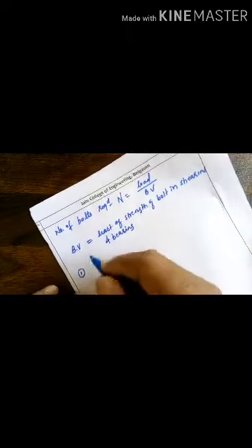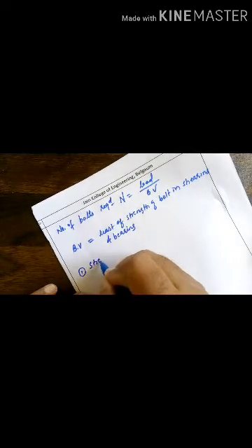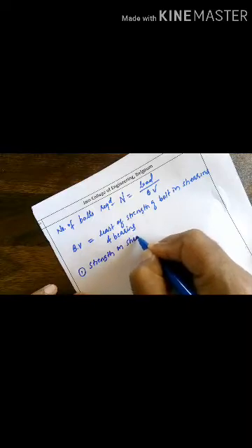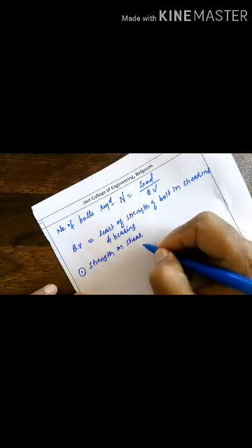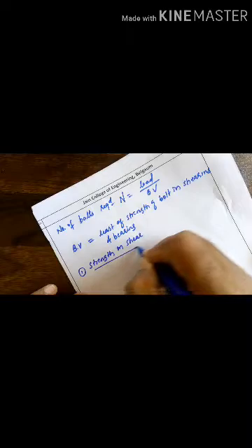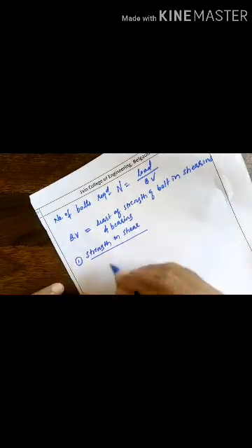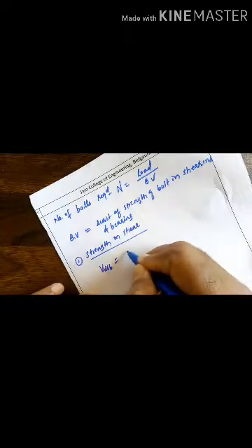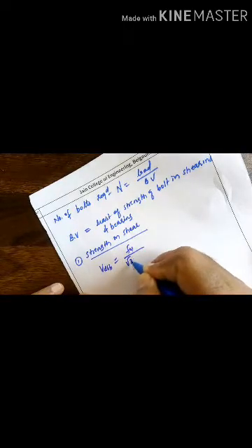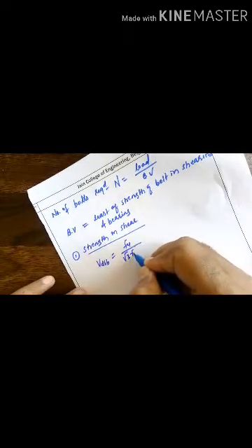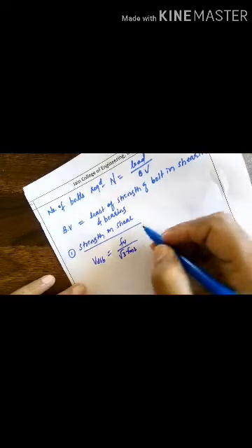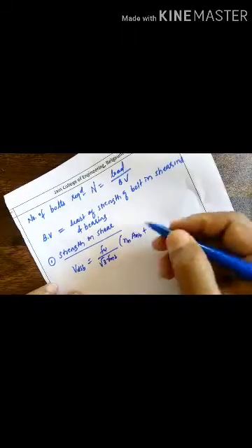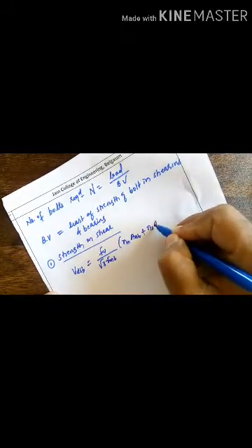So let us calculate strength in shear. The formula is Vdsb equals fu divided by root 3 gamma mb into bracket nn Anb plus ns Asb.